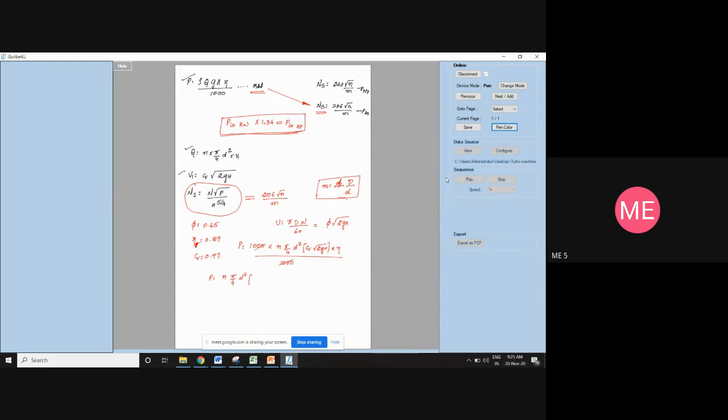Into Cv is known. What is Cv? 0.97 root of 2 into 9.81. Whether H is known? No, H is not known. So I'll take it out separately. Root of H. Into efficiency is 0.89. So if you simplify, what will you get, can you tell?